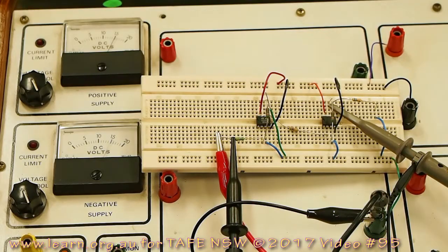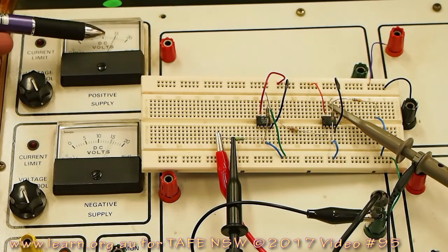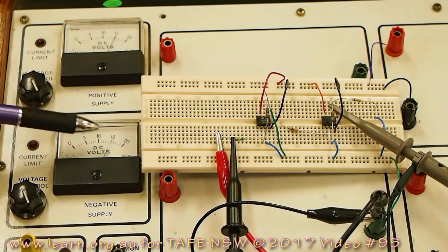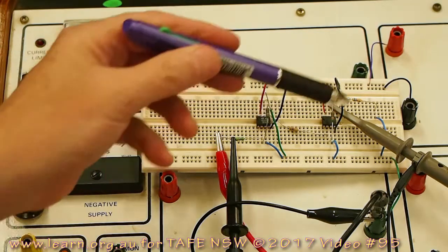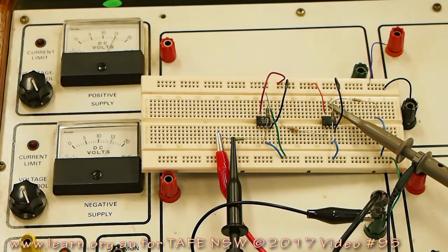Okay, here you can see clearly the setup that we're using today. We've got the two 741 operational amplifiers, and we do have a split rail power supply unit. So I've got 15 volts positive, 15 volts negative, with a common 0 rail in between the two. So I'll zoom in and we'll have a closer look at the amplifier proper, and then we'll go to the oscilloscope waveforms and the frequency comparisons to have a look at that slew rate.